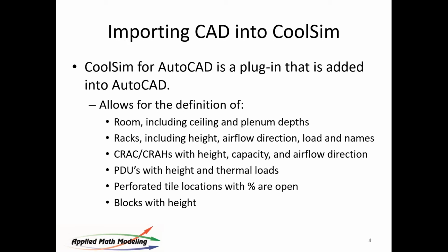So the AutoCAD plugin sits inside AutoCAD and allows you inside AutoCAD to basically set the whole model up, including height and plenum depth and rack height and CRACs and PDUs and perforated tiles and blocks, all inside AutoCAD. And then you export it. So I'm going to show you a demonstration of that.